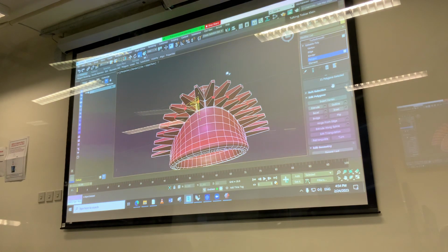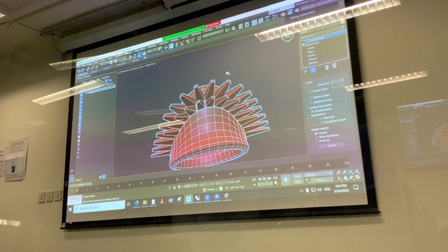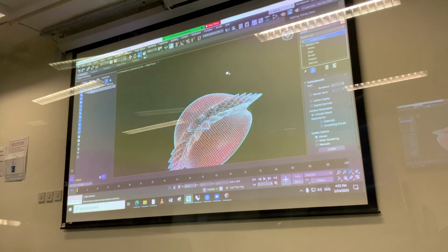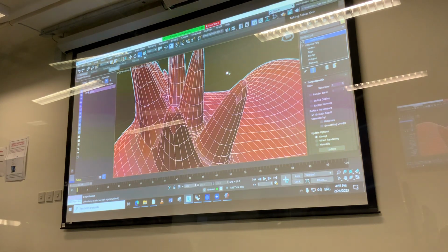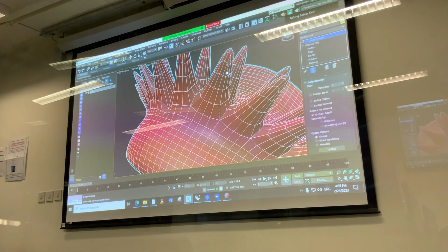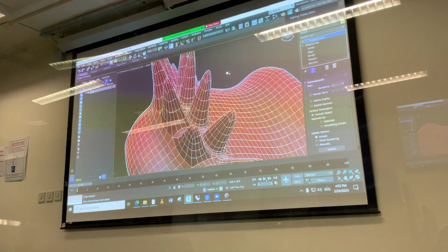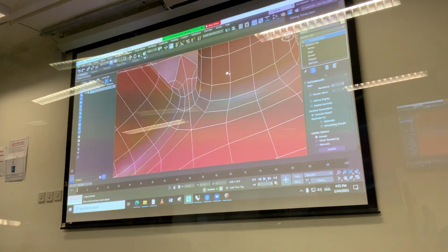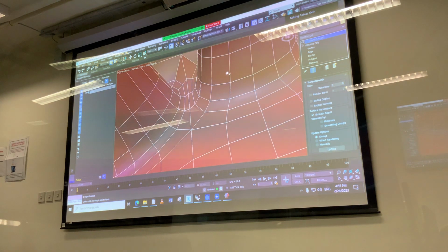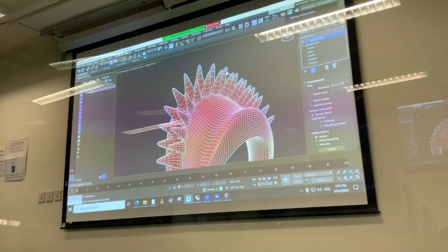Okay, good. Now let's look at how this would look if we switch on the turbo smooth. Now you see having added that inset basically means that you have a clearer definition on the bottom here, because the subdivision of the polygons means each polygon gets negotiated into 4 and then into 8. But if you have a small polygon as an inset here, see, there's a small polygon, then smoothing that would just make this stronger as an articulation.